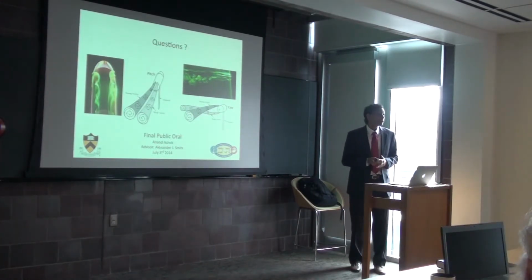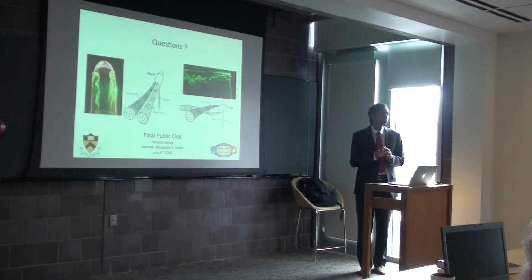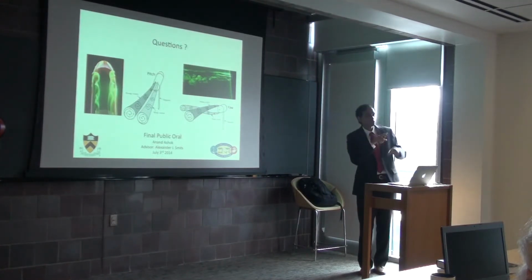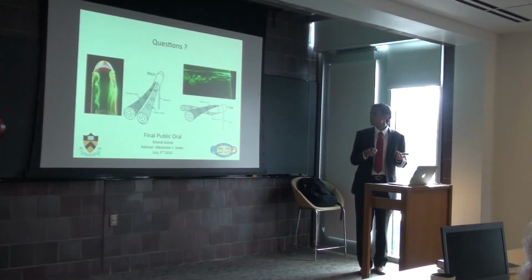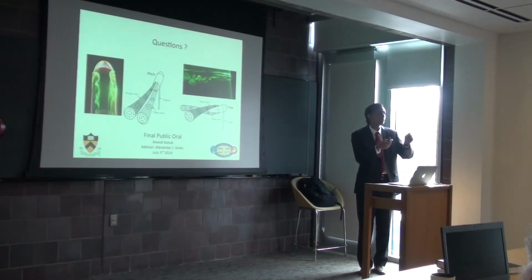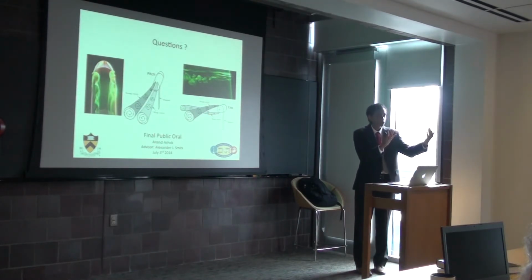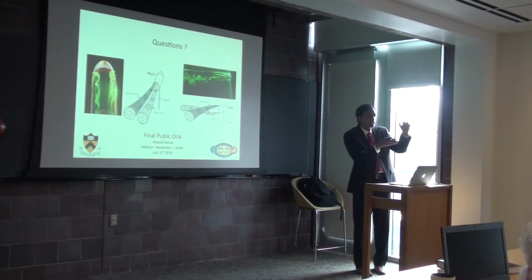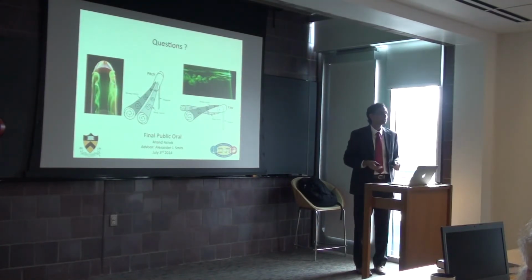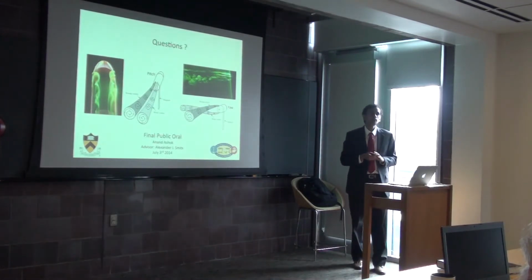That's a good question. You would have noticed that both in the low-speed wind tunnel and in the high Reynolds number facility, the submarine has a preference to rotate clockwise. Not entirely sure why that's the case. Obviously, differences in separation location is what's causing this asymmetric pattern, but why that was chosen to be on the opposite side, I'm not sure. In the surface roughness simulation, the little animation that I showed, that's exactly what I was trying to do when I put surface roughness on the opposite side. I was sort of willing the flow to separate earlier on one side rather than the other. But that didn't quite pan out.